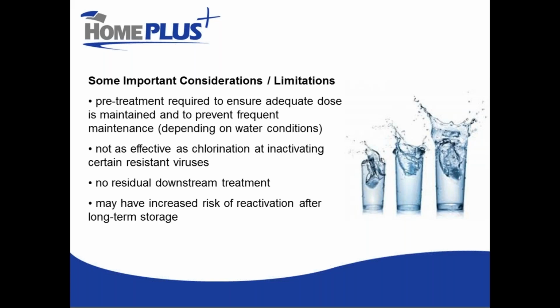There's also some possibility of reactivation after long-term storage. So we do want to be careful, if UV is our only form of disinfection, that we don't store the water for an extremely prolonged time, because there are some microorganisms that are able to repair their DNA. This would be primarily multi-strand DNA organisms that are able to do that. So just something to be aware of.